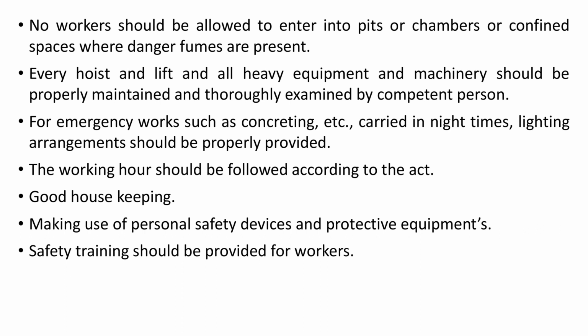Every hoist or lift and all heavy equipment and machinery should be properly maintained and thoroughly examined by a competent person. For emergency work such as concreting carried out at night, lighting arrangements should be properly provided. The working hours should be followed according to the act. There should be good housekeeping at the site, making use of personal safety devices and protective equipment. Safety training should be provided for workers.